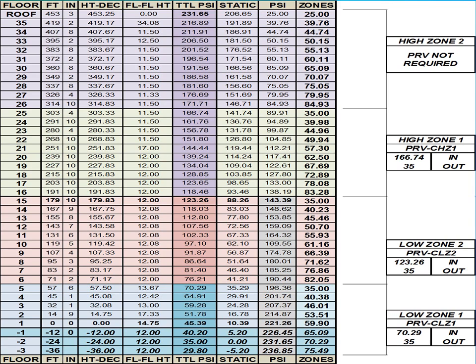So you could do this with similar results, up feeding the zones or down feeding the zones, or you can take one floor and up feed to one zone and down feed to the other with 2 sets of PRVs in the same PRV closet. Don't forget that PRVs have relief valves and must have a floor drain. Otherwise, you'll have problems if they fail open, and they have to have a relief valve to dump the water.